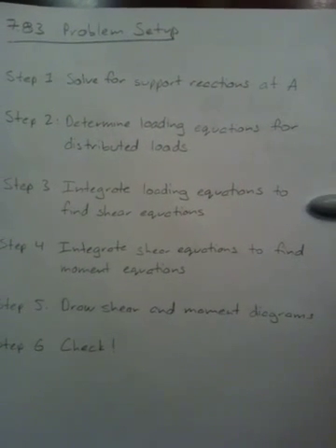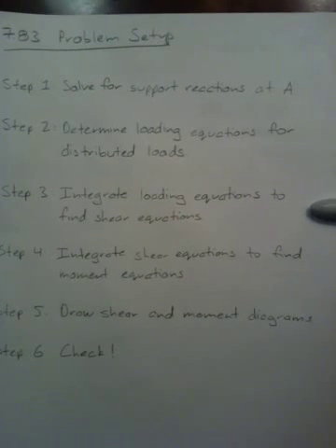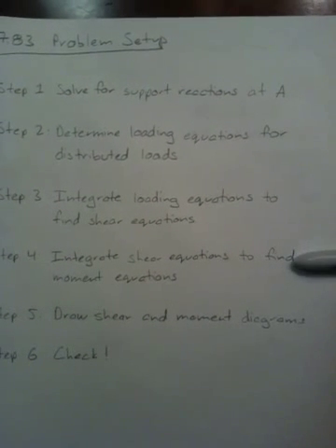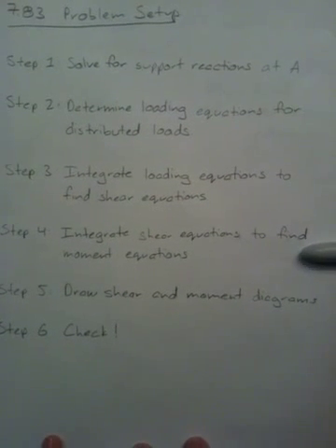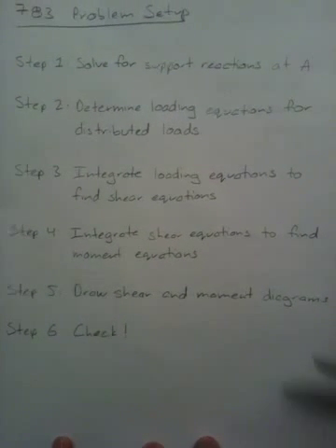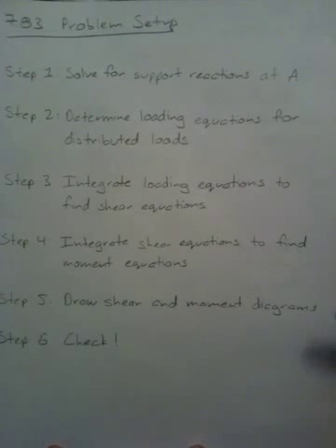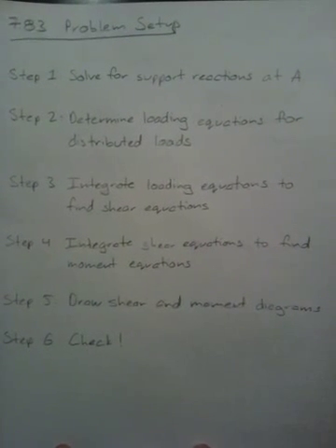Then we'll integrate those equations to get the shear equations. Moving on, we'll integrate the shear equations to obtain the moment equations. And finally use all that information to draw the shear and moment diagram. And of course our final step would be to check our solution.